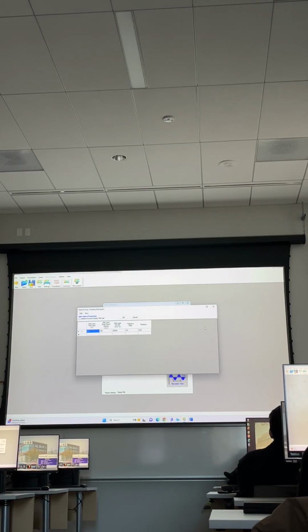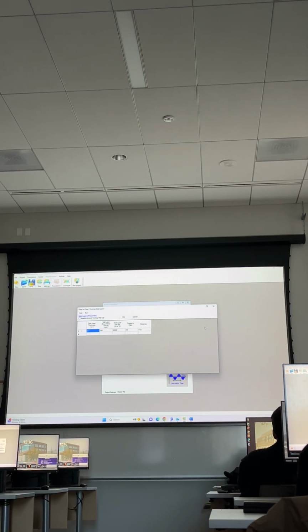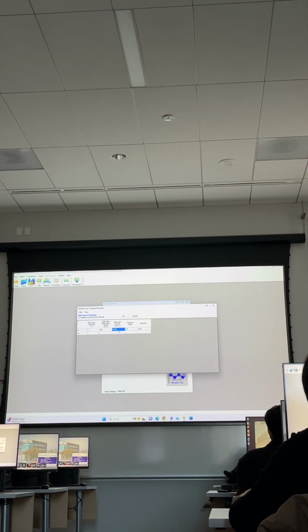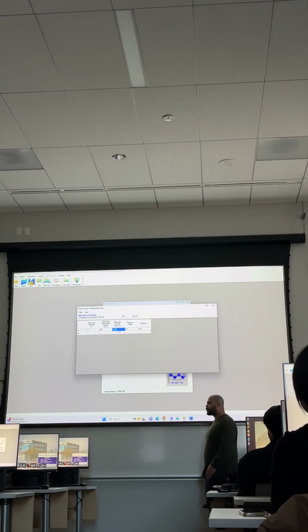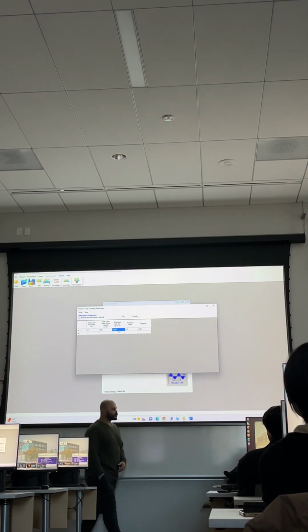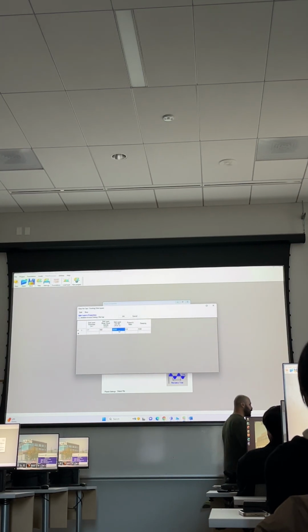Let me this time define it as structural fill. The structural fill, as I told you, has a shear wave velocity ranging from 350 up to 400. So we can change this to 350. If you want to keep it as 180, that's okay. It's fully okay, it's granular fill. If you want to change it, it's up to you. You can actually study